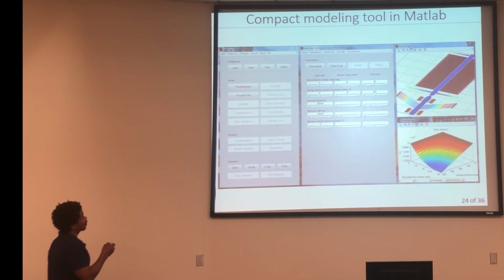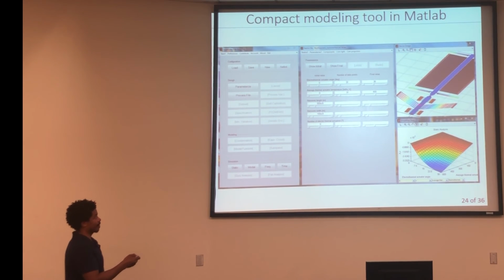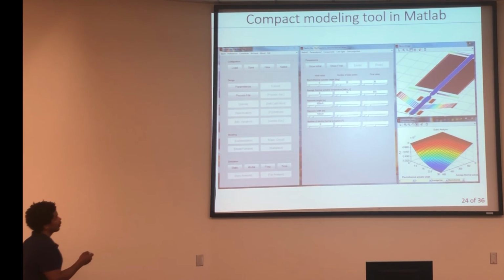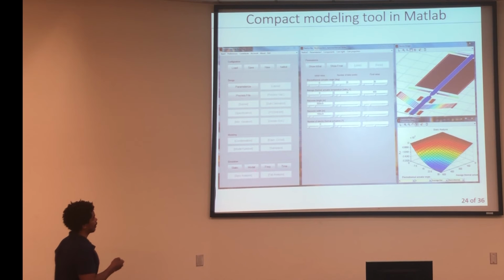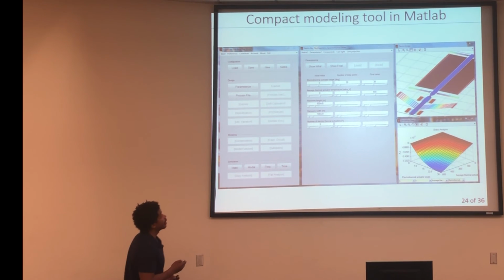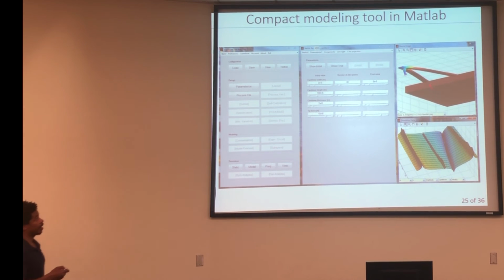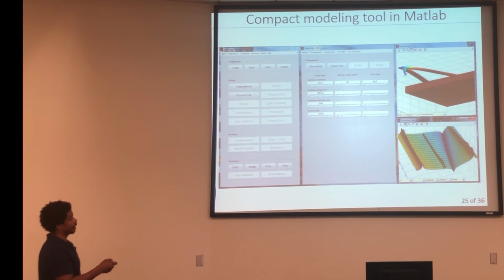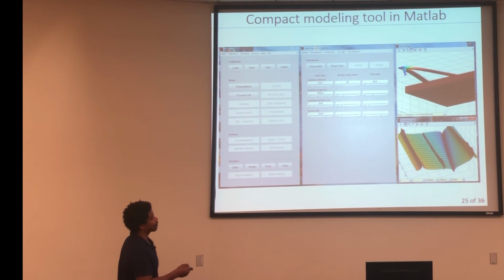Then for your design, you pick your process file, which tells the tool the Young's modulus, the coefficient of thermal expansion, all your material properties. Here's some modeling, and then you simulate it. You can do static analysis, modal analysis, frequency, or time domain analysis. Here's another one, an atomic force microscope. Here's a probe tip, held by two cantilevers. And here I'm making a Bode plot, but manipulating a couple of parameters while I make that plot.